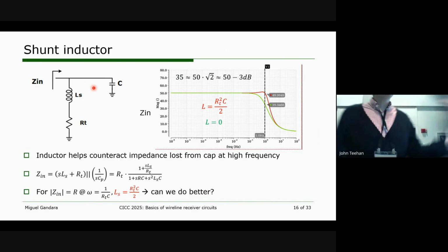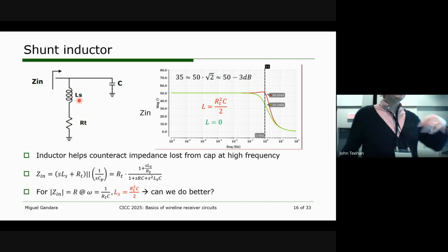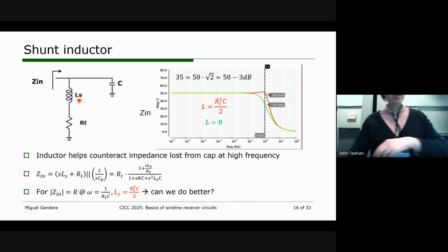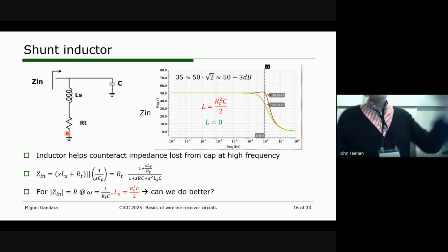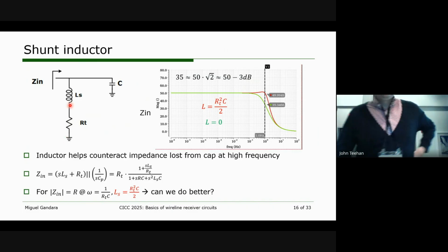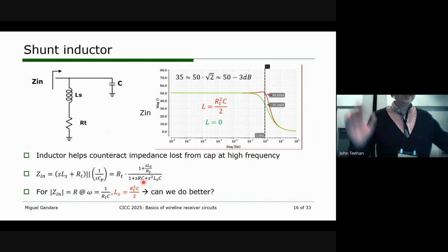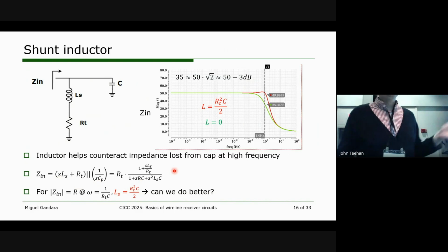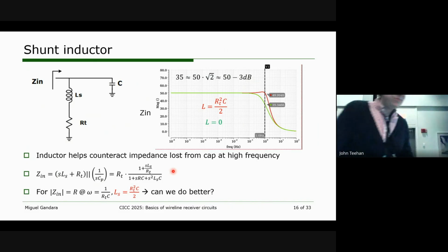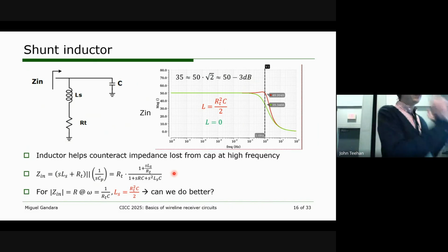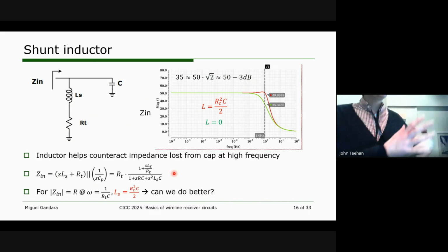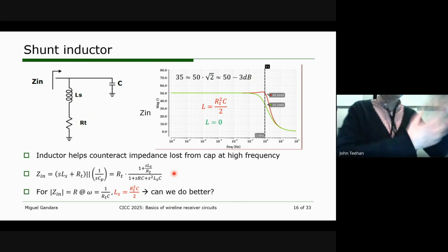That's because at high frequency, the inductor turns the circuit into an open circuit. At low frequency, we have the termination resistance. At high frequency, we have an open circuit, okay? And now, of course, this is in parallel with the capacitance. So when we combine this series impedance with the parallel capacitance, we get this expression, okay? Now we did the algebra, we have a polynomial. Let's try to take that polynomial and relate it back to the physical world, because that's how we build intuition, right?